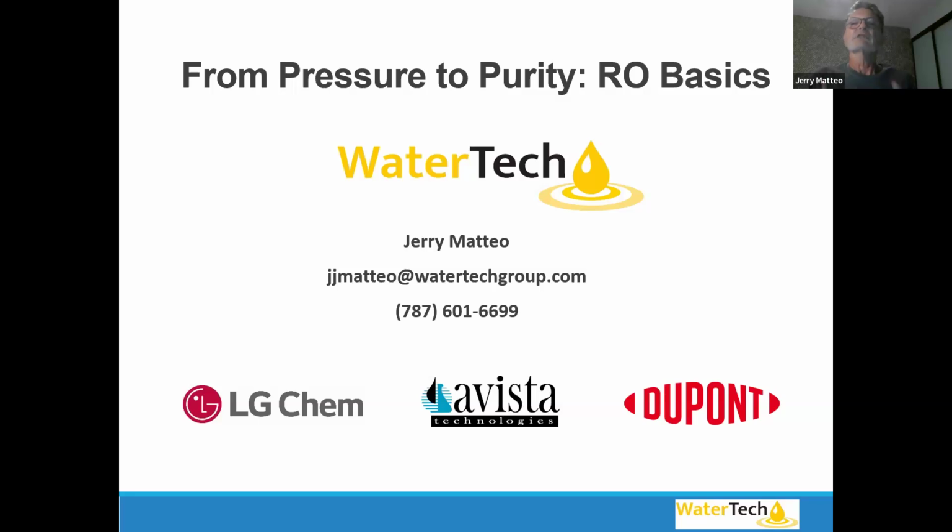That's good. But from an anti-scaling point of view, because I'm a chemical engineer and we do a lot of the chemical treatment on ROs, sometimes I call them, don't take this wrong, whoever's calling in, the worst of both worlds. Ocean water is going to be primarily salt as your dissolved solid, and salt does not scale. Even as we concentrate, it doesn't really scale my membranes. A beach well could have silica, calcium carbonate, iron, manganese, a lot more minerals than you're going to have in ocean water. So, back to Timothy's point and yours, we've got to profile that water. You want to see a good water analysis from your beach well.